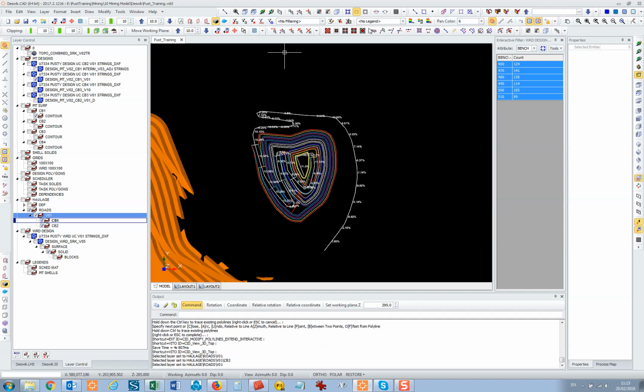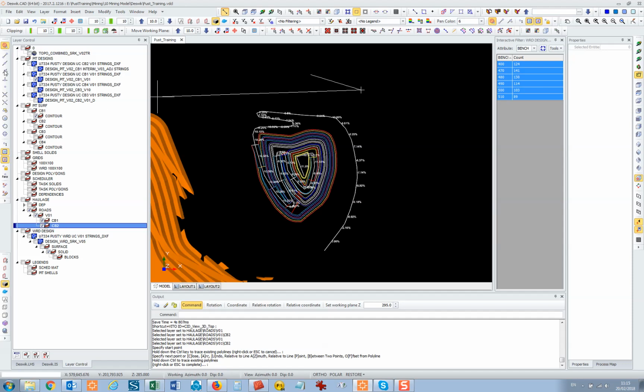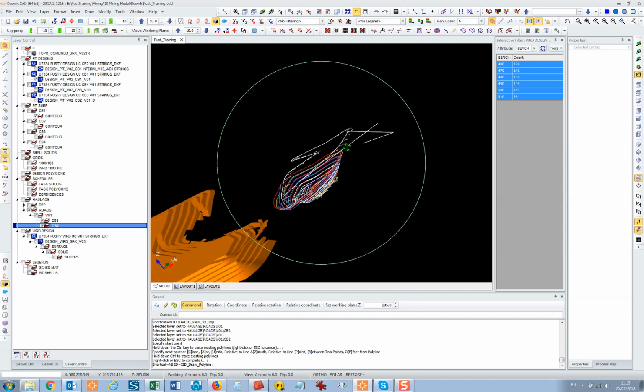And if there are roads which overlie each other, you can, if you hold down Control when you're inserting points and click, I'll just show you quickly, just as an example. If you go line, if I've got a line here, but if I click snap to points, if I hold down Control and click, it just automatically follows. Right. And if I click again, then that's actually, you know,